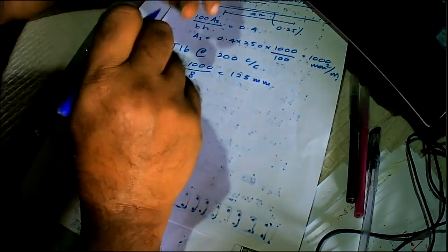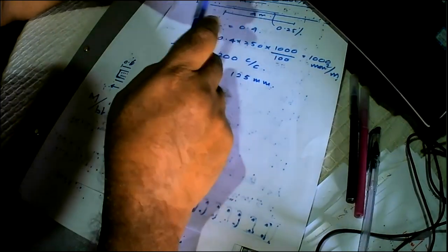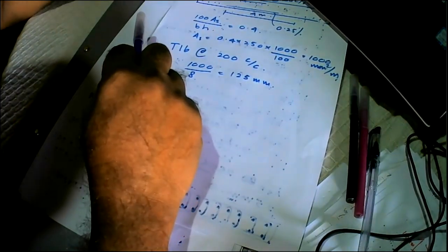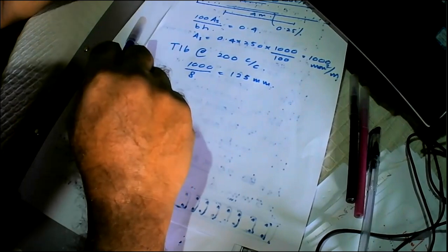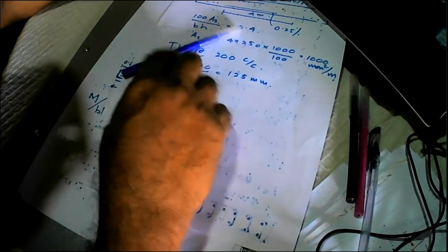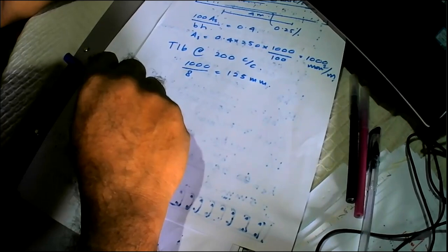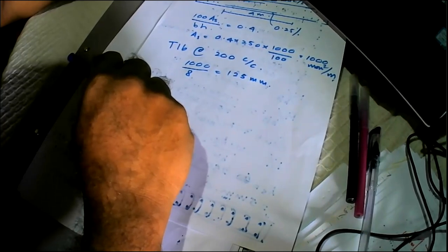Yes, if you want, you can even go for something like 0.6 meters and concentrate it. But trying to concentrate too much means there will be a lot of congestion of reinforcement at the ends of the wall. So that's why we go for a reasonable length like 1 meter for a 6-meter wall.